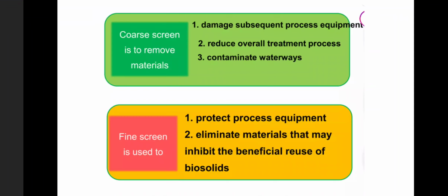The influent cover initially stops the floating materials, and the guide track helps rotate the stainless steel screen elements, which collect the floatable materials. With the help of the drive motor, they rotate, collect, and take away the floatable particles present in the wastewater, which are collected in the doctor blade assembly. From the doctor blade assembly, it is taken to the dumping yard. This is the continuous belt screen.